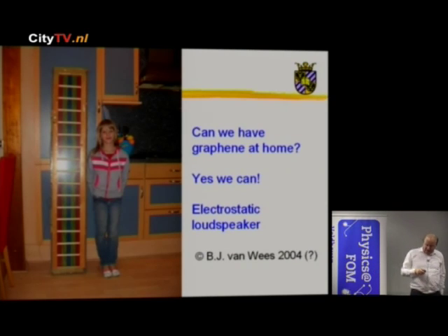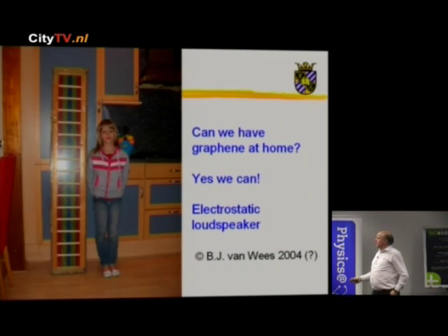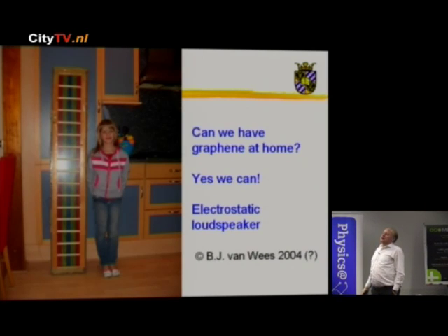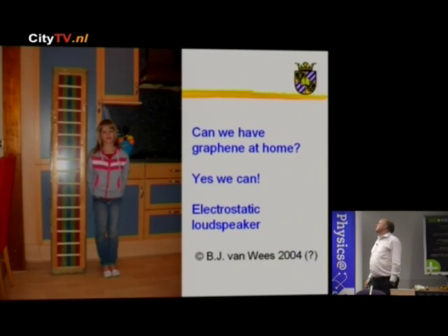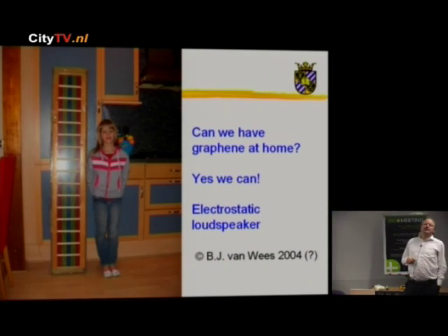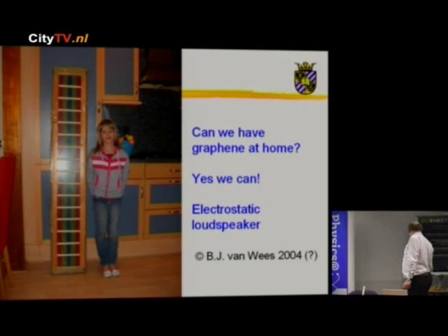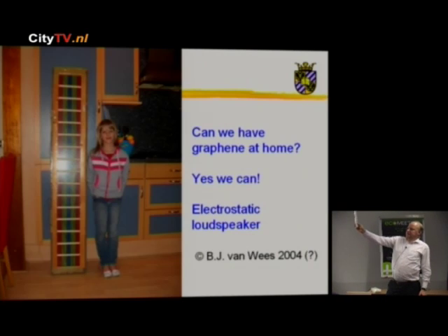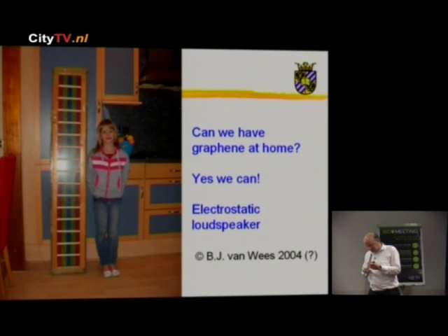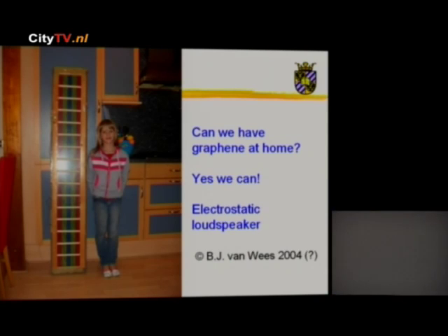The nice thing, of course, is that it can be relatively light compared to regular loudspeakers where you really have to move much more mass. Here this membrane can in principle be very, very light, so you can have high quality sound reproduction. Well, I was just interested in the principle, and I didn't want to spend too much money. So that is why wood, etc. And for the membrane I used kitchen foil, like this. You can really stretch it. Of course, it will tear after a while, but you can really stretch it, as you know.